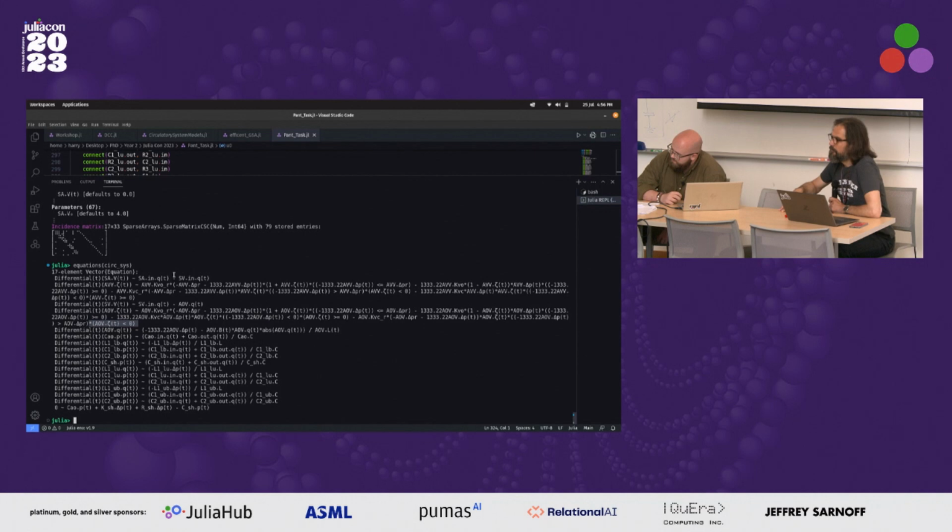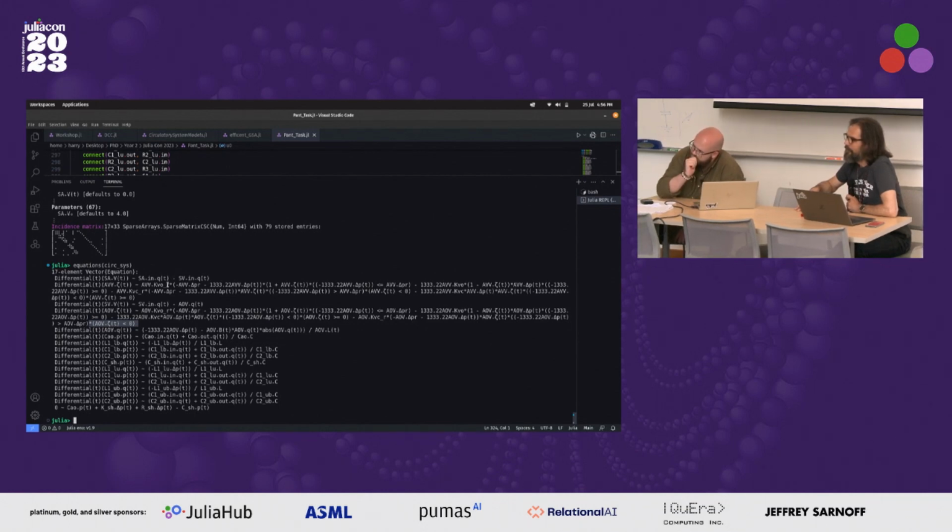Maybe just a small thing concerning the hard stop and also performance. An hour ago, approximately, you said that it's not possible to implement the diodes in an ideal way. If you have a look at the Modelica implementation, it is implemented ideally using a characteristic curve.